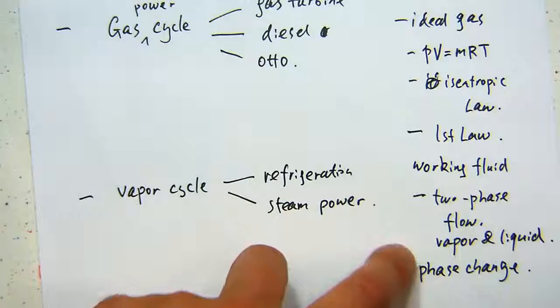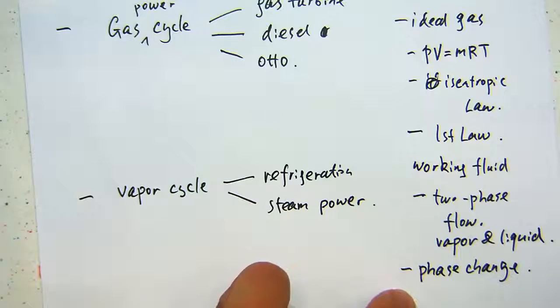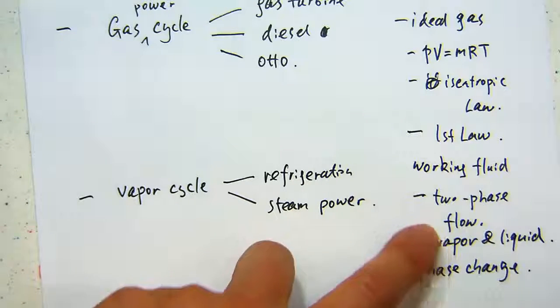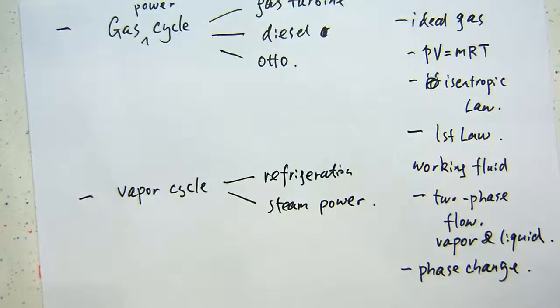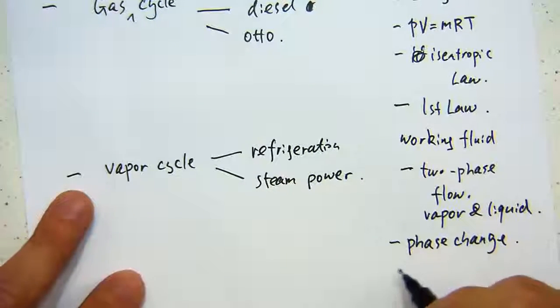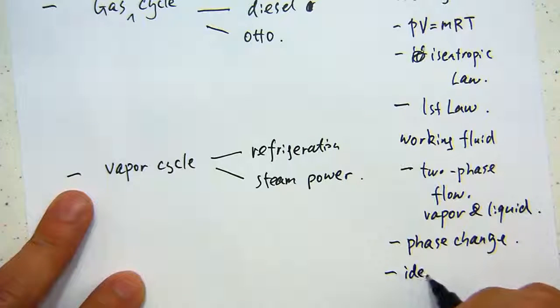And here the important thing to notice is that when we're dealing with vapor as in single phase, so for certain process they're only involving vapor in the process, but you do not want to apply the ideal gas law to the vapor. All right? Even though it doesn't involve two-phase flow, only involving the vapor, the ideal gas law does not apply. So that's something you want to be aware of.